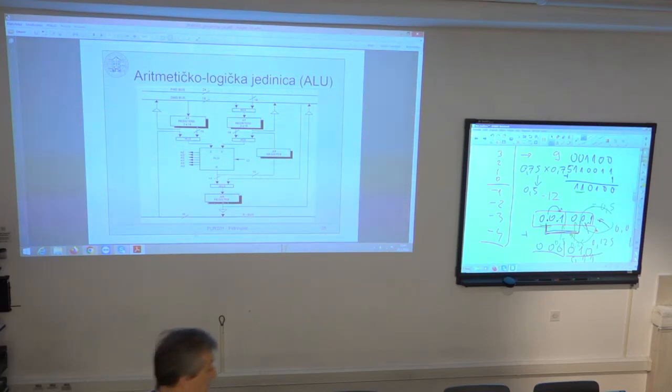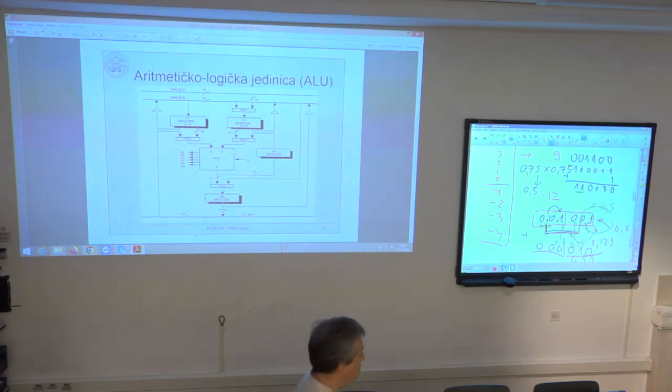What it means is that it has a mirroring set of registers. There are actually two sets of registers. One is like a background set of registers, and the other is like a foreground set of registers. And I can toggle one single bit in one control register of the CPU to exchange these two sets.